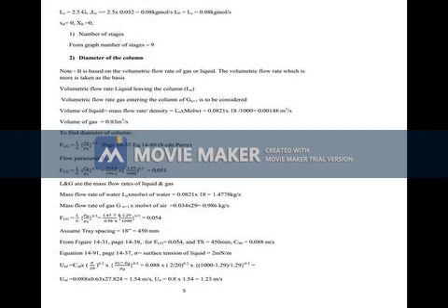That is the volume of the feed entering the column, given as 3000 meter cube per hour, which is V, notation Vn plus 1. That gas which is entering into the column has the subscript n plus 1. Since it is volume, we put it as Vn plus 1. What we require is Gn plus 1, that is molar flow rate.